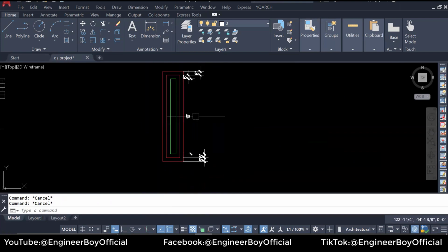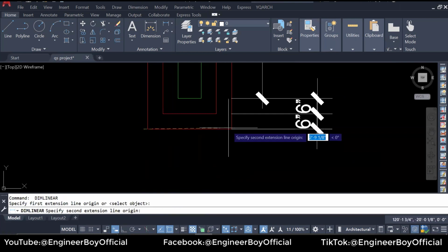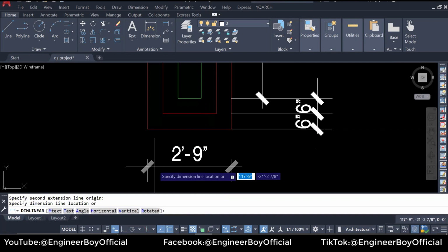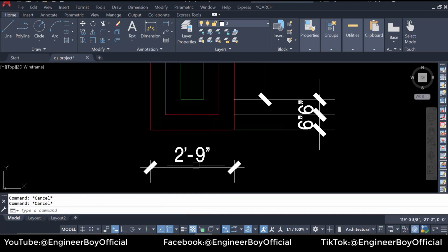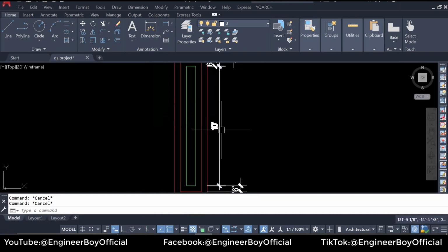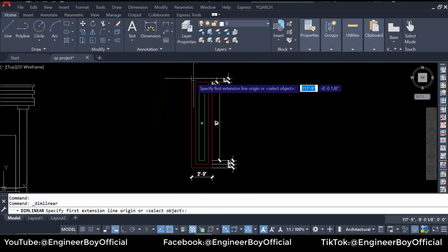As you can see, this is the width of the foundation, which, if I'm not wrong, is something like 2 feet and 9 inches. What we do is subtract the wall thickness from the foundation width. If you subtract 9 inches from this width, it becomes 2 feet only. Then of course we add the length of the wall, so 2 feet plus 10 feet becomes 12 feet.